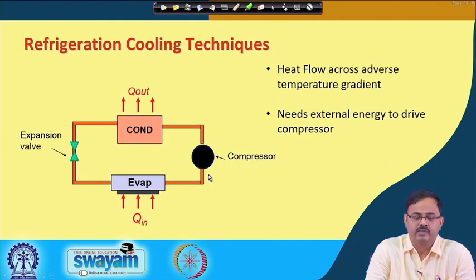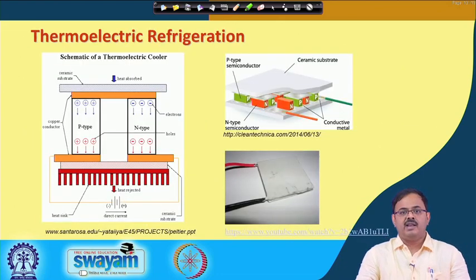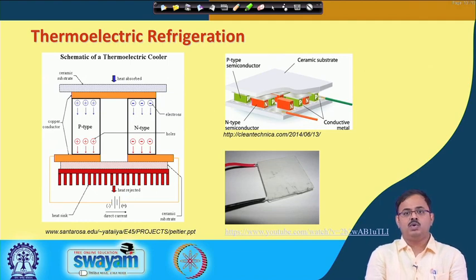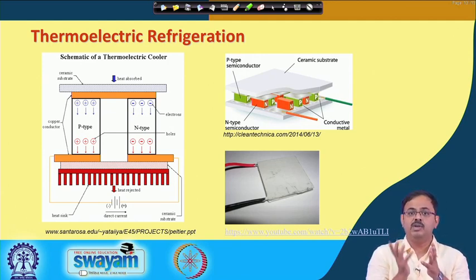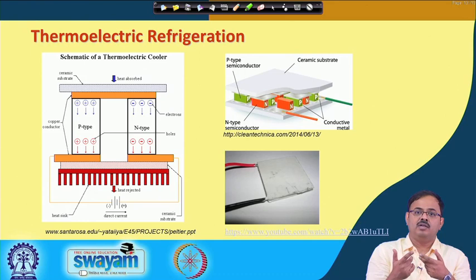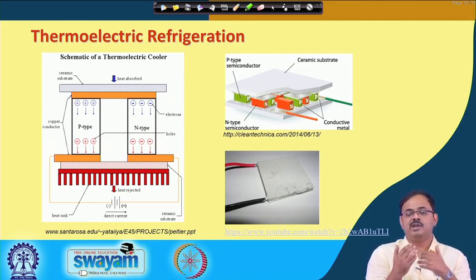All right. Another refrigeration technique, which is known as solid state refrigeration, is thermoelectric refrigeration. A thermoelectric cooler, by the way, thermoelectricity, as the name suggests, is thermal and electrical. It can work both as a generator of electrical power, or given an electrical power, it can lead to a temperature difference.